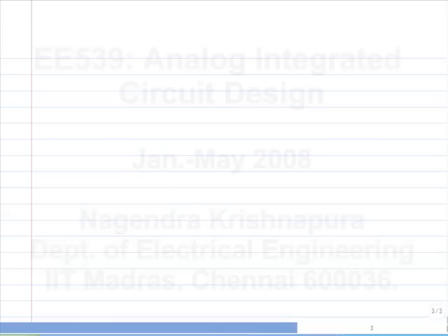And as far as amplifier design is concerned, we would like to design the system with either no ringing or just a little bit of ringing, and again either no peaking or maybe just a very small peaking in the frequency response. Okay. So we will certainly not want the imaginary part of the poles to become very large compared to the real part. Even if it doesn't become unstable, that's not a condition that we would like, because if the imaginary to the real part is large, that implies a very high quality factor. That means a very low damping factor. So that means also a high amount of ringing in the step response.